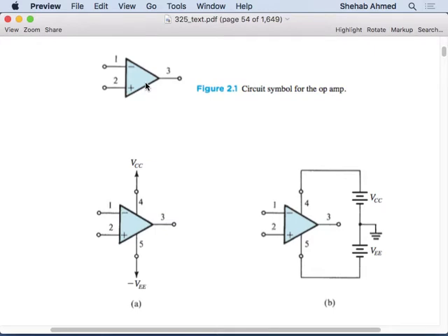So some op-amp chips will have frequency compensation inputs. Something else, sometimes you have an input called offset nulling. Sometimes the signal will have the measured physical phenomena, and as well maybe some shift, because your circuit itself caused a fixed voltage to be applied to one of the op-amp terminals somehow, by electromagnetic interference, by capacitance, whatever it is.